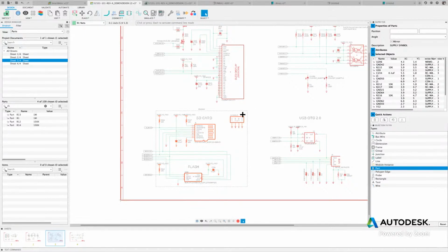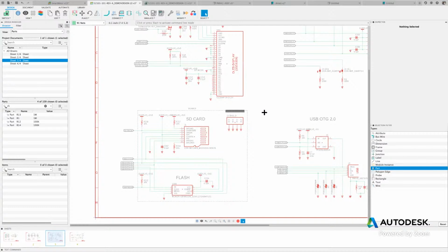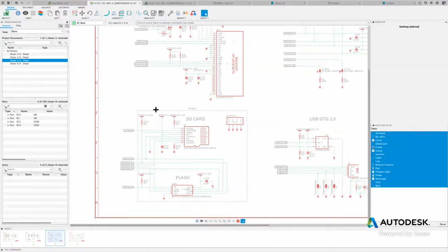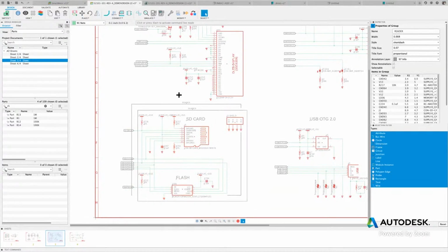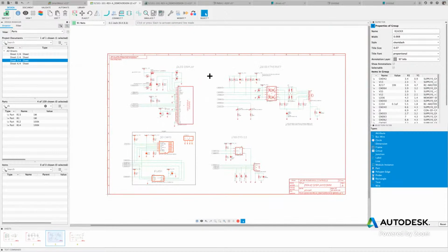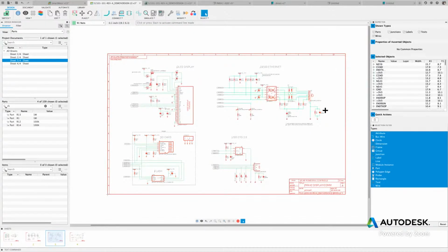Now, if I need to move this module throughout my schematic, I could just select the component. Give me one moment. Oh, I have to reset. Okay. So here we go. So now I'm able to move that group depending on its functionality. So I could keep them neatly organized. I could keep on doing more groups depending on their functionality. Usually it's done by functionality. So as you see, I create the group, I right click, I select new group, call it Ethernet. Okay, so there's my group, and I could keep on categorizing each one of them.